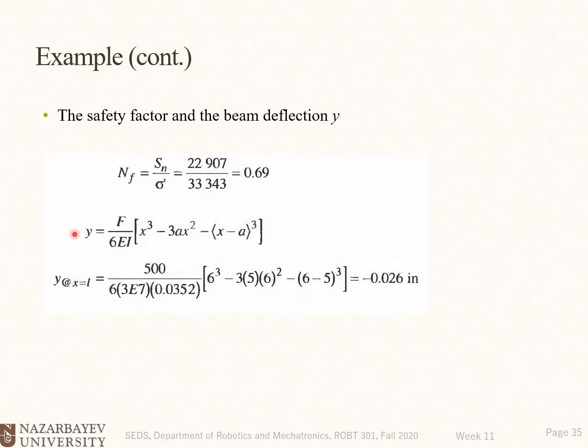Since the deflection also is important to us, you could either use a singularity function to calculate the deflection, or you could refer to the appendix of the book to see the formula for the deflection for a concentrated force at the tip of a cantilever beam, and calculate the maximum deflection of the tip.